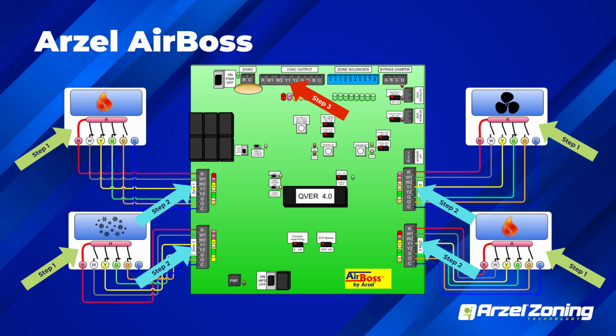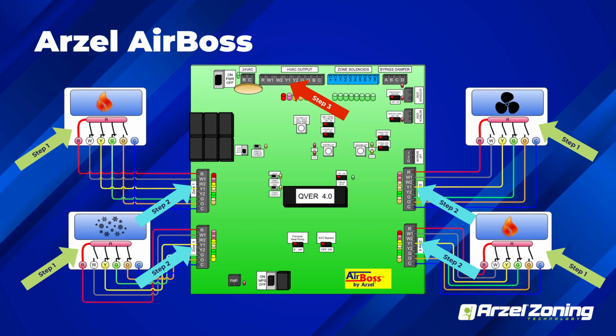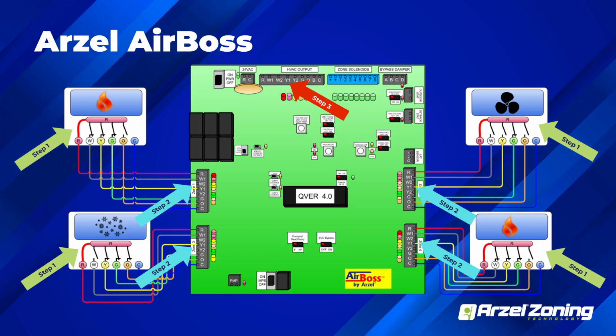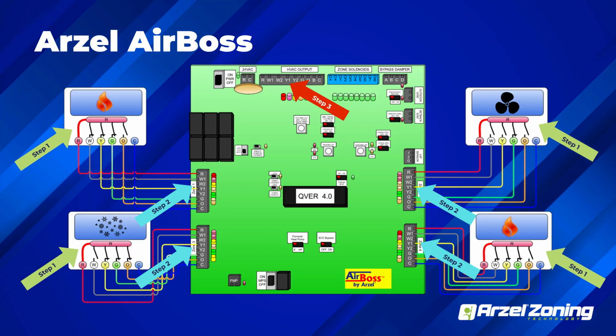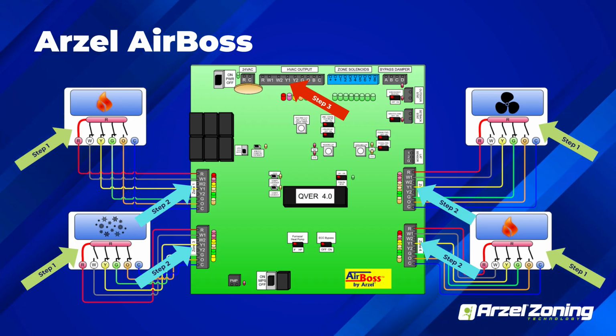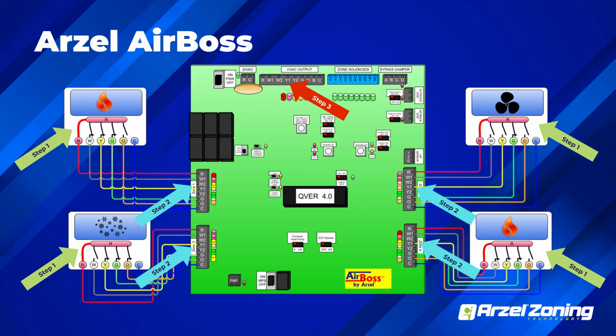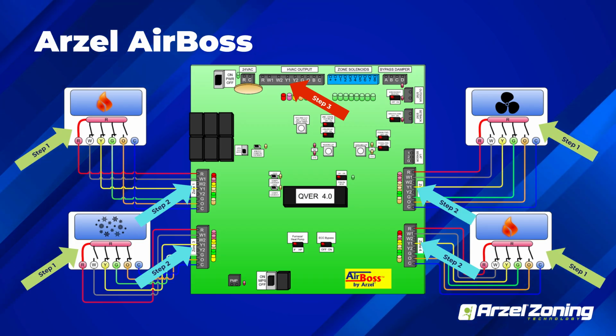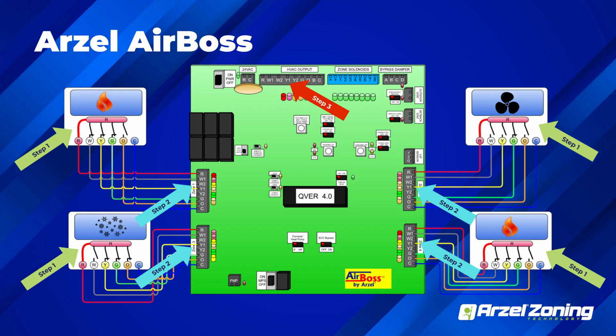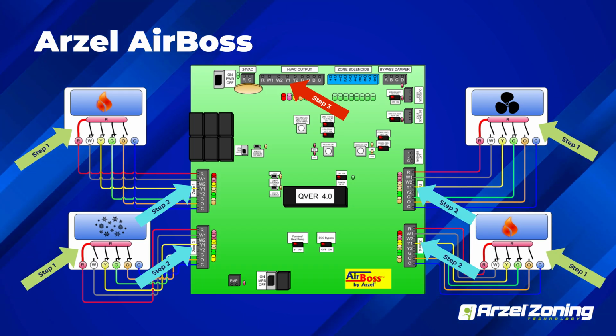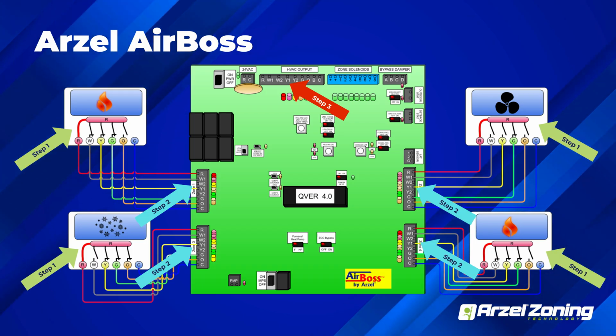The panel is going to have several diagnostic lights on it. It might be first and second stage heating, LAT, might be compressor lockouts. So the panel does have indicators to tell you that it's got something disabled. There's reasons for it. And if you're confused when you're looking at it in the field, reach out to us.